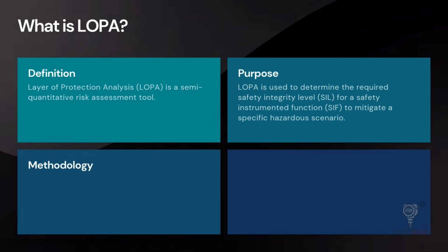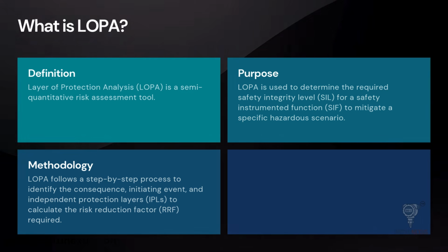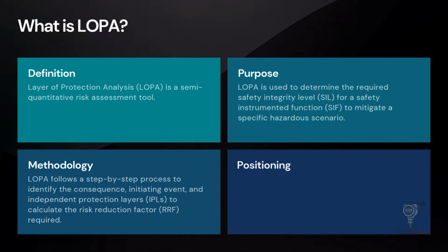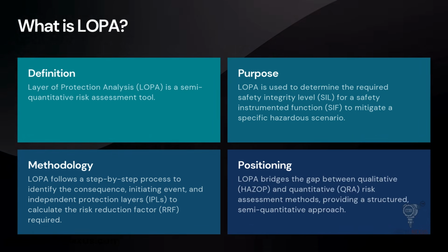The methodology is disciplined. We identify the consequence, pinpoint the initiating event, identify independent protection layers, IPLs, and calculate the gap. It bridges the gap between qualitative HAZOPs, which rely on opinion, and complex QRAs, which rely on heavy statistics.